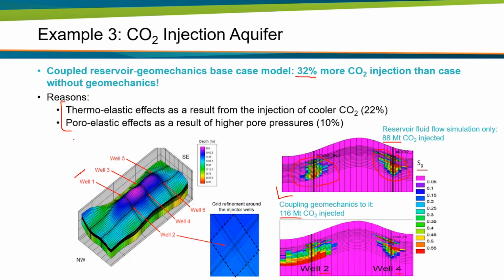And so now in this particular case, there was a fear that if this fracture is growing here, it could actually fracture into the overburden, into the caprock. So in order to avoid that or minimize the risk, there was the idea to perforate only the lower half of the wells, and in perforating only the lower half, we would expect that we can inject less CO2, so we give up a bit on the CO2 injection, but with the purpose of increasing the safety.